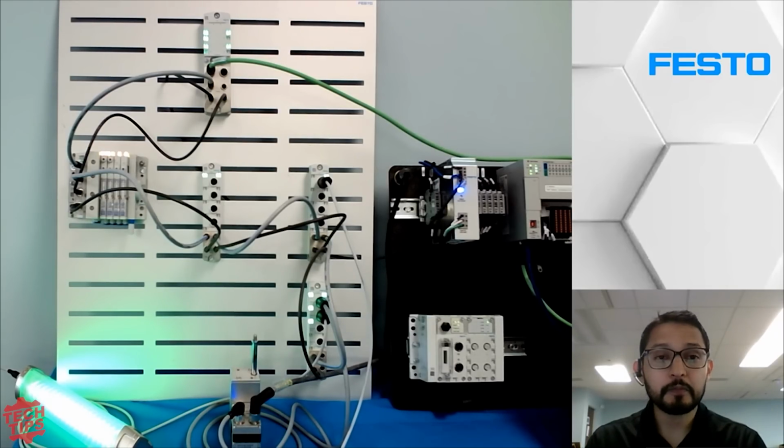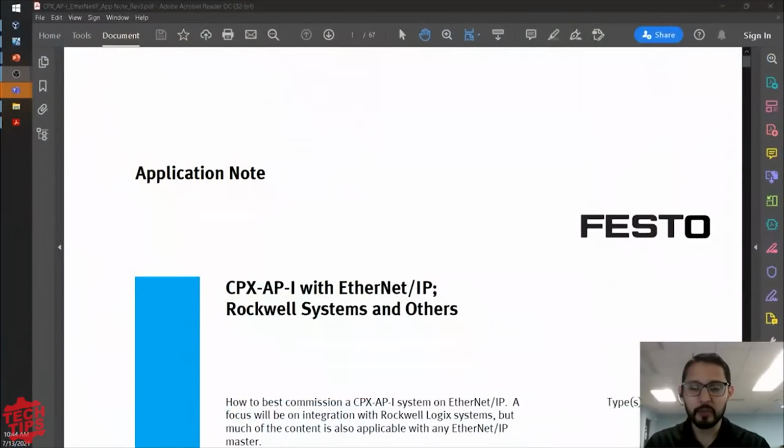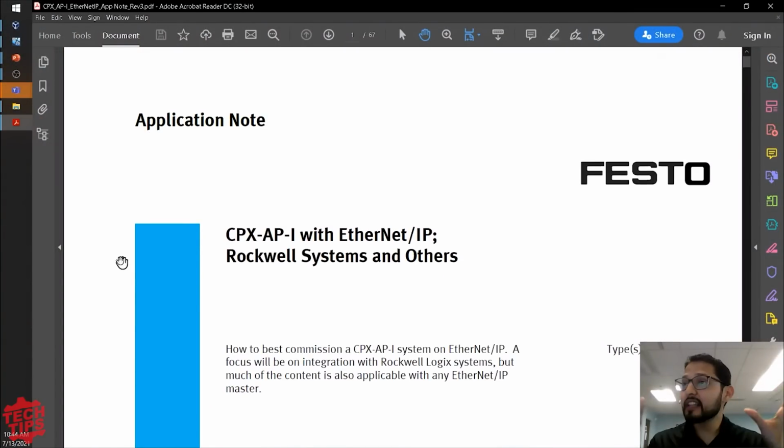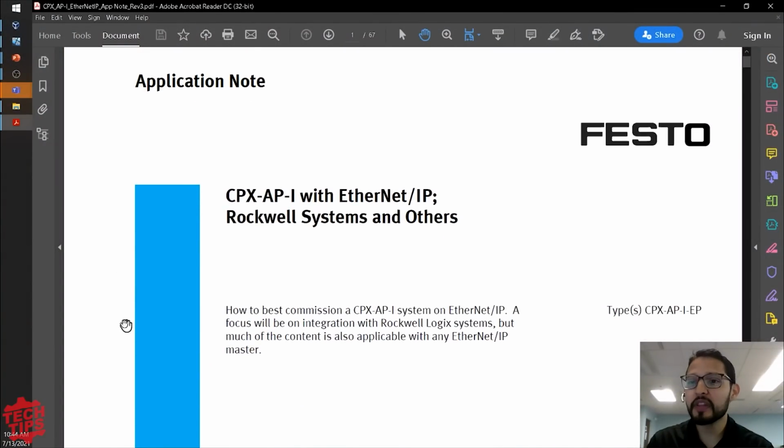Before you go show that, I just want to throw out a disclaimer. If you're going to use an L18 with 80 of these modules, do not buy the hardware before you do it, because while you will have enough Ethernet IP nodes and AP nodes, you may run out of memory. Because there's not a lot of memory in these little PLCs. So build everything up offline and make sure you have enough memory, because these little guys, these L18s, L16s, don't have a lot of memory. You may get all your UDTs in there, but you may have no room to program left. That's an excellent caveat. Excellent point.